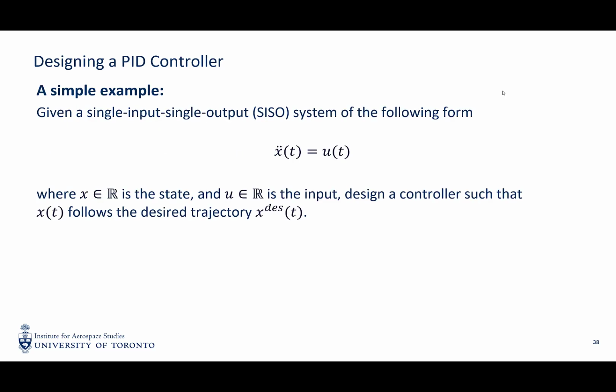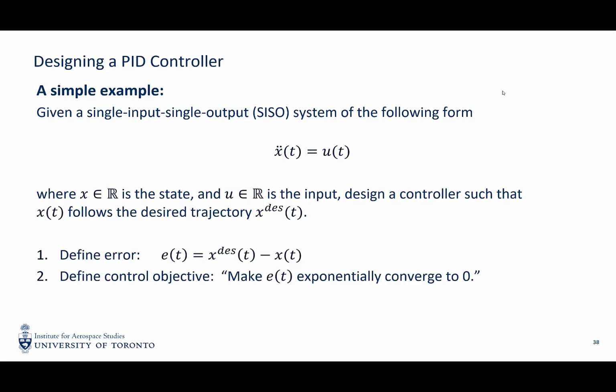Okay, so I will cover several topics about PID control and LQR, and also give you a brief introduction to nonlinear control in the implementation part. PID is the most commonly used one. A simple example is here. If we have a double integrator system, x double dot equals u, and by defining a position error, E, as the difference between your desired position, such as a trajectory, and the current position, we want to compute u such that this E goes to 0 as time goes to infinity.